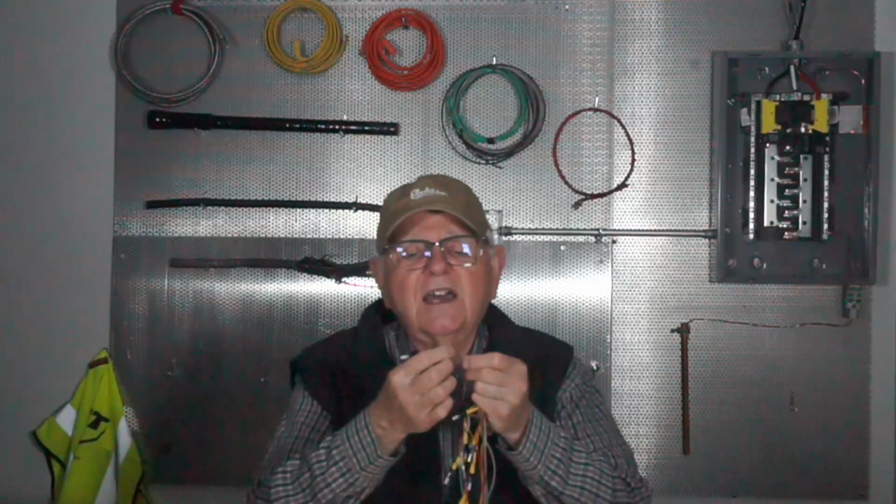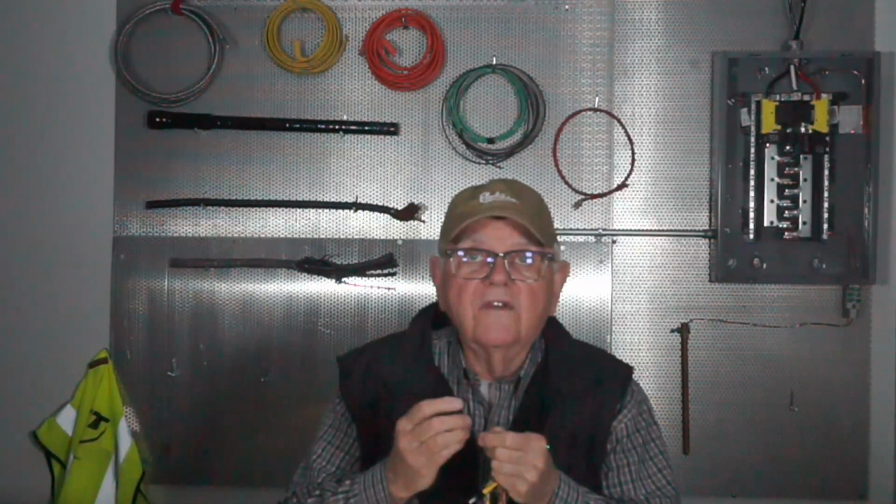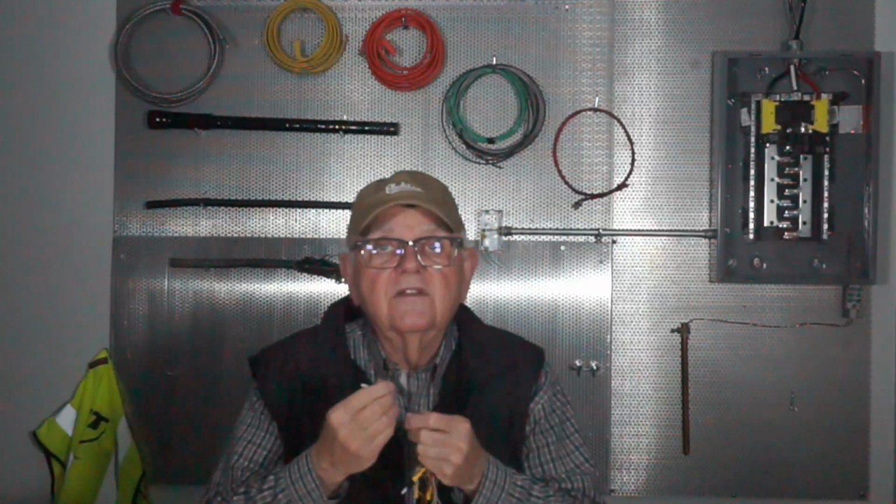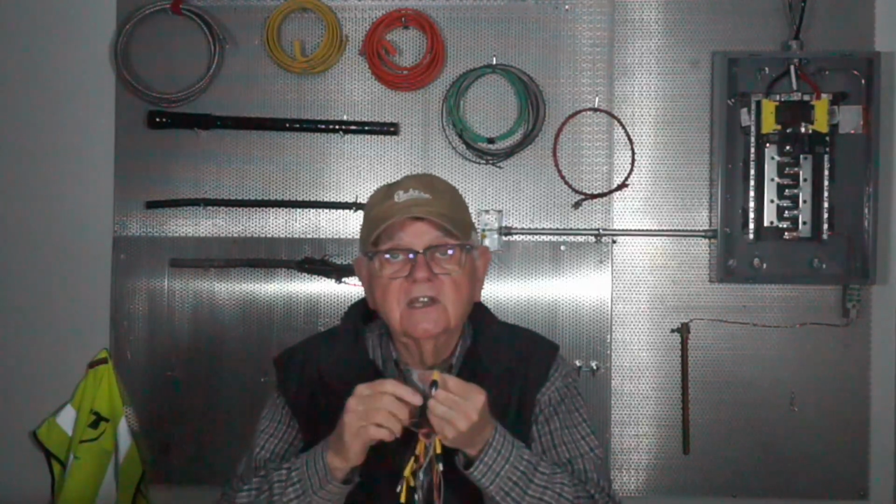If you want to learn how to put these terminations on the end, you're going to need to take some special training to do that. You're going to need the special tools. You're going to need a cleaver to cut the cable. You're going to need a special device. As fine as that jacket is on that individual fiber, you need some type of tool that'll take that jacket off and not damage the glass. You're going to need to clean it, put a boot on there, and then put whatever type of connector you're using on the end, and then you're going to have to put it into a special device to lock that fiber optic core and cladding into that connector.